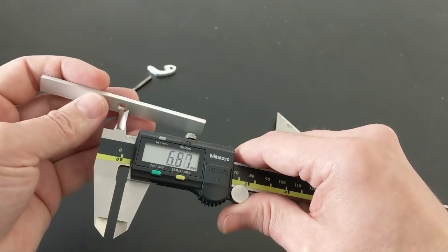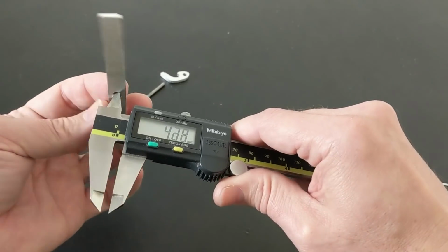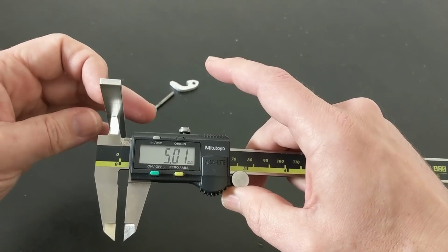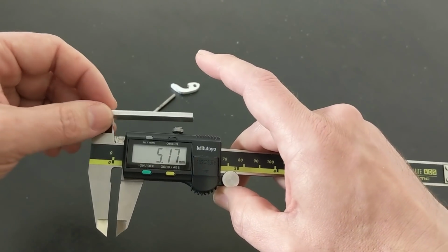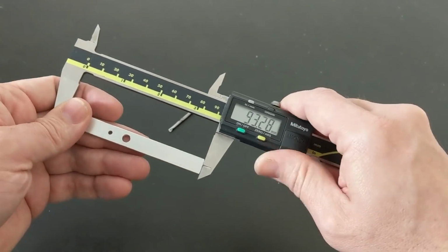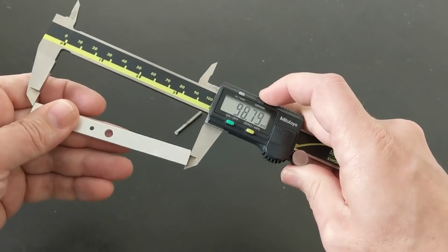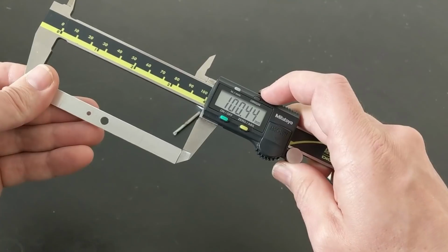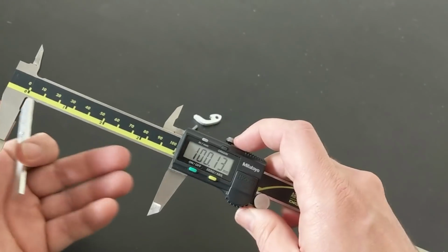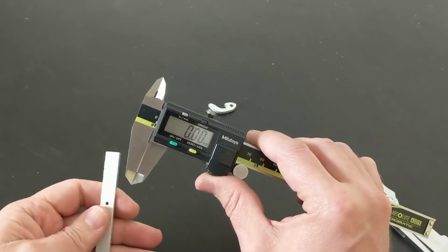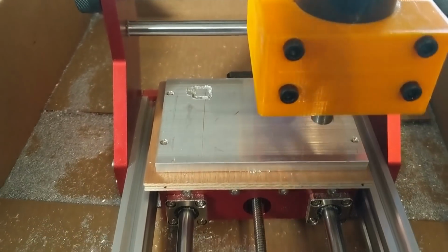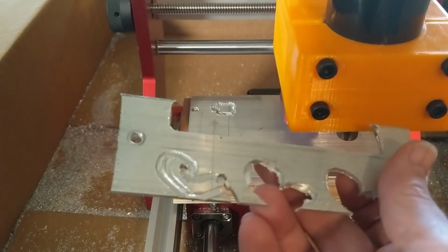But it gets even more interesting because here in the hole, this is meant to be a 5mm hole, and you can see it's almost perfectly on in the y-axis, and in the x-axis, it's again like 5.2. But the x-axis was the one here that was really quite good as far as accuracy goes in that direction. So it looks like my tolerance on this machine is plus or minus 0.2mm. So that's 2 thicknesses of paper, and that's pretty enormous, but I don't know, what do you expect from a $500 machine?